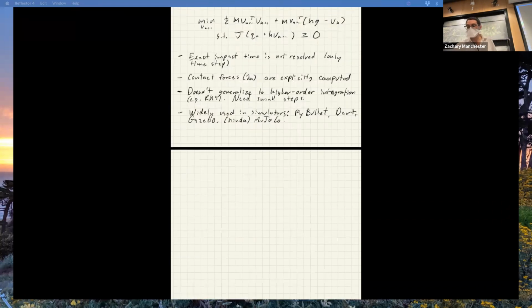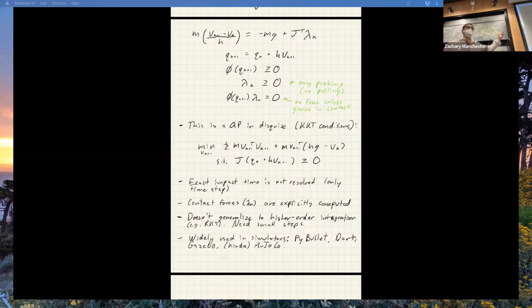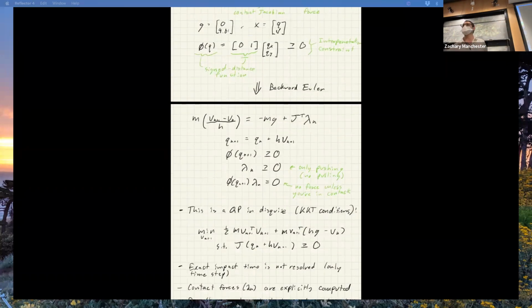Okay, next fun question. So this is the dynamics. Imagine I want to solve a trajectory optimization problem to make my robot walk. Before, I would have had my Acrobot or something, with nice algebraic conditions from taking the ODEs and applying RK4. Now my dynamics constraints are this whole set of KKT conditions. In principle, I can do that, but does anyone have any thoughts on why that might not work super well?